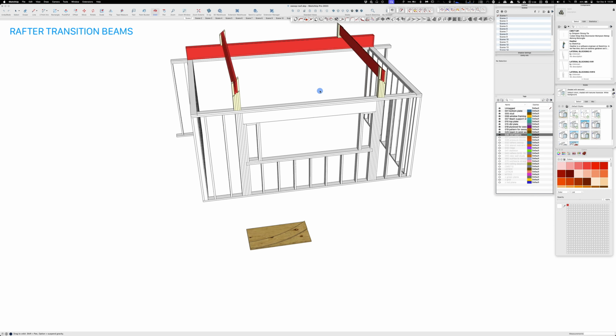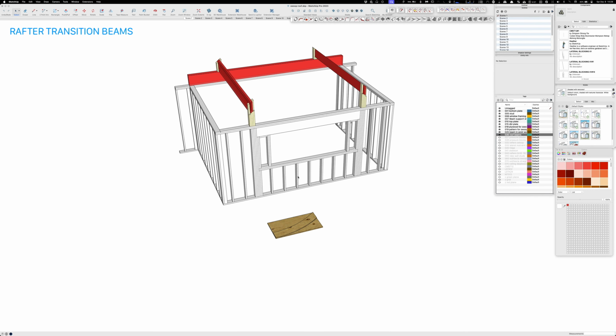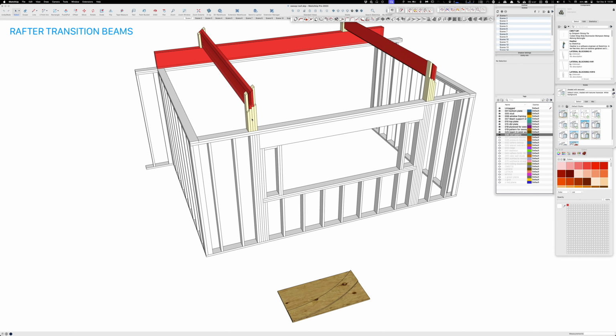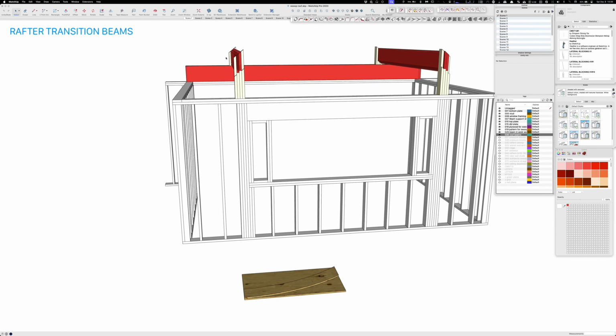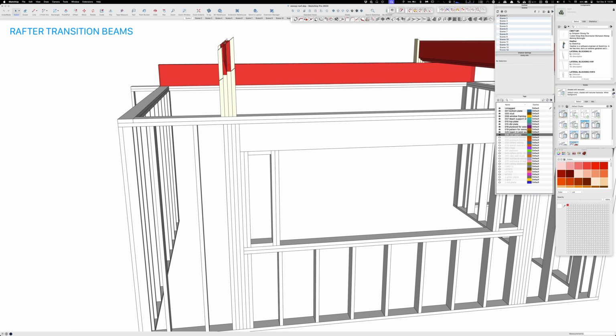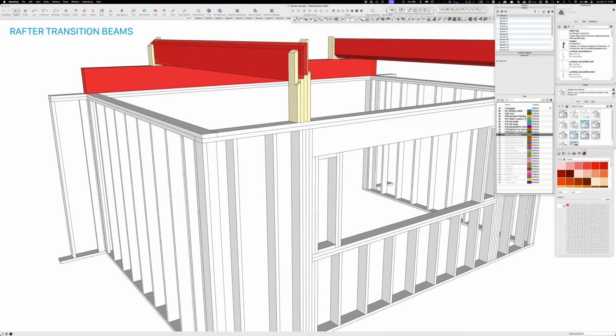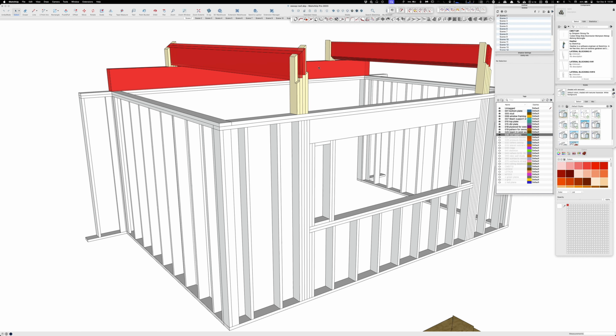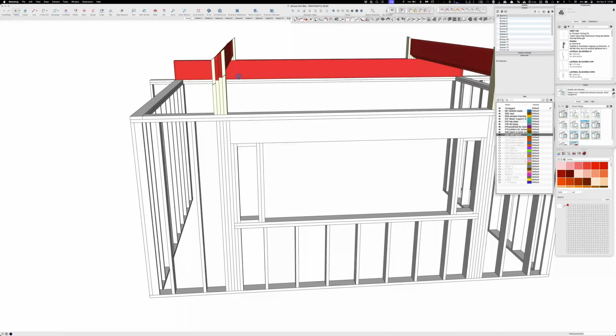Then you're going to need beams that are going to hold the two different types of rafter. You'll have a conventional straight rafter on one side and a swoop rafter on the other. And so to get these angles and stuff, you're going to need taller than what you expect. So I figure 14-inch LVLs with 8 and 12, or correction, 10 and 12, I think is what it looks like. I could be wrong, though. There wasn't a lot of technical detail.